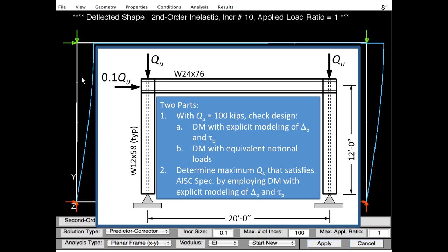The other thing about rotating those columns is I'm having the student check the columns. They're actually beam columns, right? And I didn't want them to have to worry about lateral torsional buckling of the columns. By rotating them, a section subject to minor axis bending doesn't laterally torsionally buckle. An I shape subject to minor axis bending only either fully yields or is fine. So you don't get lateral torsional buckling when you subject a member to minor axis bending. So there were two things I was after there to keep this problem simple enough so the student could get the big picture and the understanding.